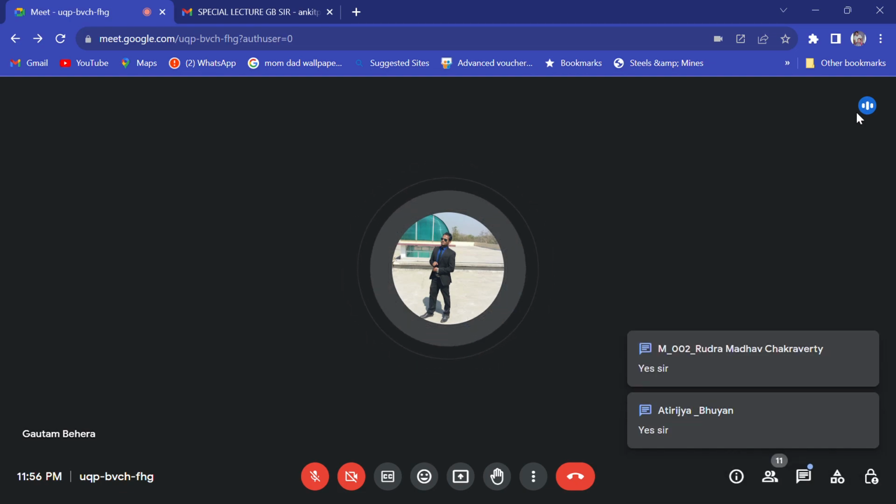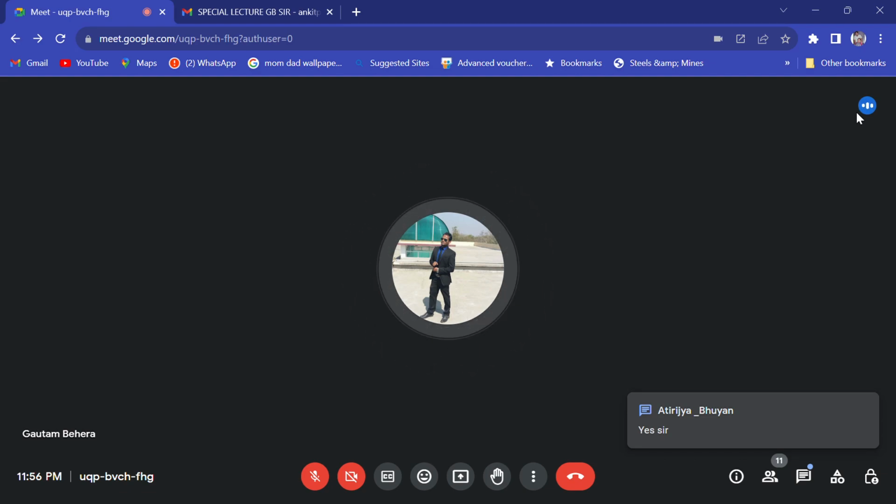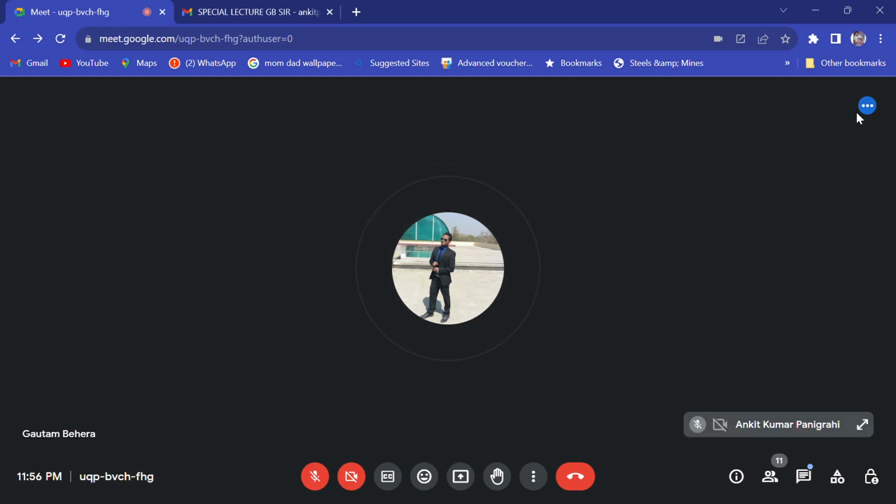Okay, fine. And the other thing, you can increase the hot blast temperature. The hot blast temperature you can increase to a large extent. You can go to 1200 degrees centigrade, right? So that means you are inputting some amount of heat already. So less heat will be required inside the furnace. Already we are putting some heat. So the burden on the coke will be less.